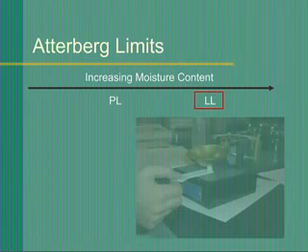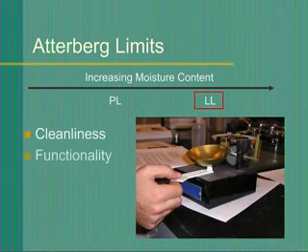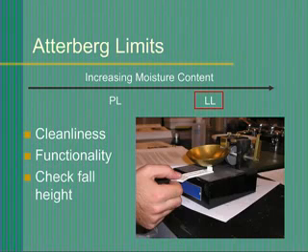Next, check the liquid limit device. Inspect the device for cleanliness. Check for proper functionality, ensuring that the cup falls freely and does not bind. Verify that the fall height of the cup is 10 millimeters.